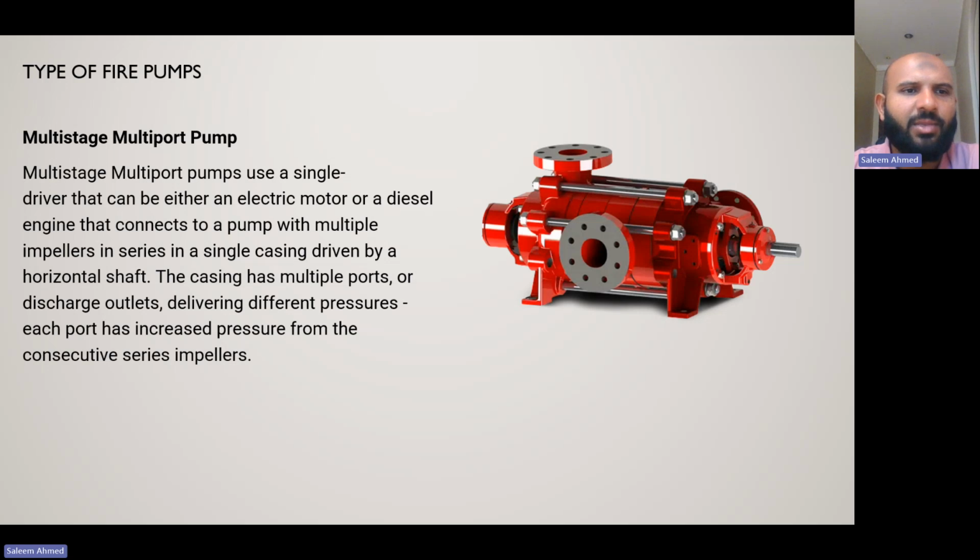The last one is the multi-stage multi-port pump. It uses a single driver that can be either an electrical motor or a diesel engine that connects to the pump with multiple impellers in series in a single casing, driven by a horizontal shaft.